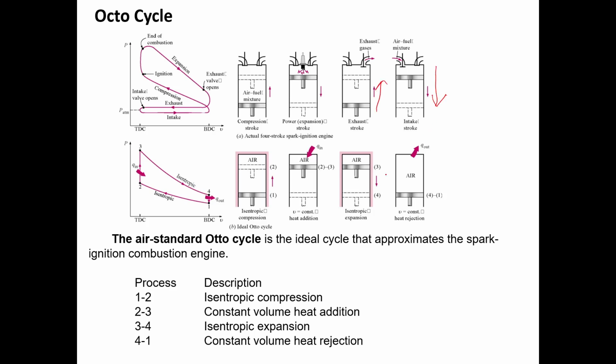Therefore when you come to the thermodynamic cycle, we omit these two things. Now let us start from the compression, from this point onward, because it is also ideal for the mechanical cycle. We are compressing this one from 1 to 2. That means we have isentropic compression, starting from here.